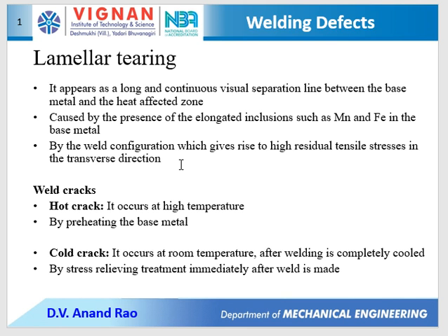Next defect is weld cracks. Weld cracks are nothing but discontinuities in the weld zone, generally resulting from stresses caused by expansion and contraction. These can be avoided by using filler metal which matches the base metal composition.